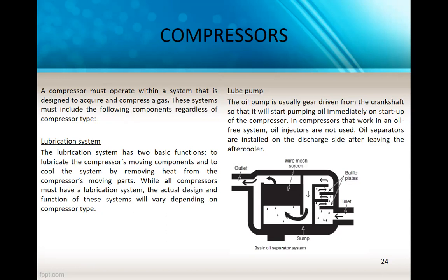Next, the lube pump. The oil pump is usually gear-driven. See the figure. The bigger one is the separator. The oil pump is usually driven from the crankshaft so that it will start pumping oil immediately on start of the compressor. The driven, it is connected to the crankshaft, so it runs together with it. In compressors that work in an oil-free system, oil injectors are not used.